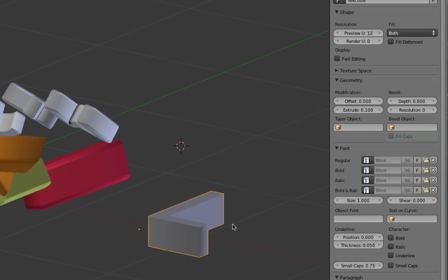So what I wanted to point out is you'll notice the edges of this thing are really sharp. So we want to add some depth to those. We're just going to come in here. We've got a bevel. We're going to add a bevel to the text, so you can see that it's adding a smooth angle, a curve to the edge. We can just pick whatever we want.